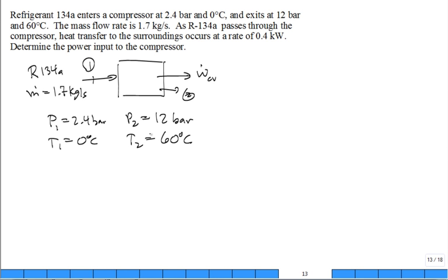Nothing. All that mechanical energy you're putting into it is increasing the pressure, but it's also increasing the temperature of that air, and you can feel it on the outlet. Go find a tire pump and do it, okay? It's interesting the first time you experience it. It's like, wow, how did that get so hot? Same thing here. You're compressing refrigerant. It's getting hot and high pressure.